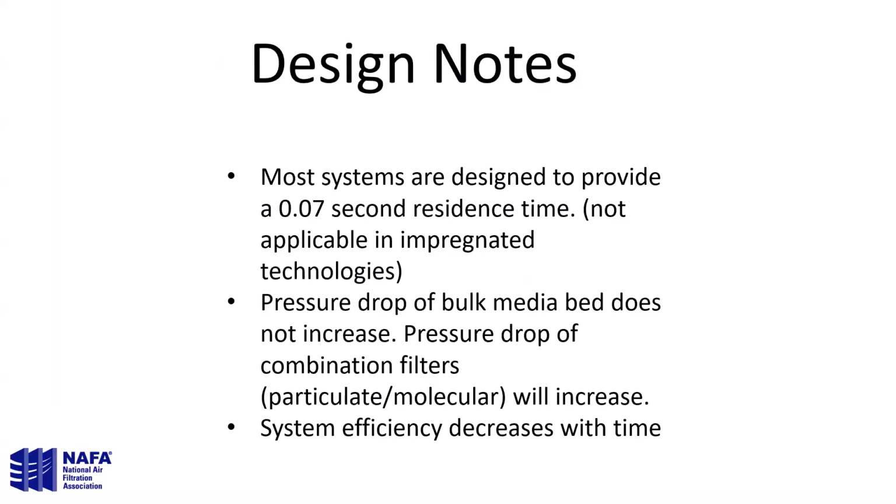This is how your systems are designed. Most systems have been designed to give you a 0.07 second residence time. And I'll explain why it's not applicable in impregnated technologies. This is for a bulk system. And that doesn't mean that you're going to get 100% efficiency. It just means that you're going to let 100% of the air actually touch the filter media. It doesn't relate to efficiency, but if you don't at least have that time, it doesn't have a chance to capture it.